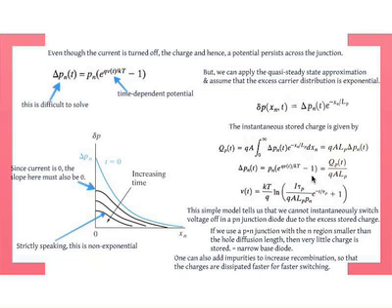Okay, then the voltage, then you can take this expression, plug it in here, and invert this equation to get the voltage. So it's pretty straightforward. kT over Q, some logarithmic factor. Okay, now you see that the transient in voltage is complicated. Okay, it has this logarithmic expression. Of course, we also have this exponential term, so it's a fairly complicated relationship.